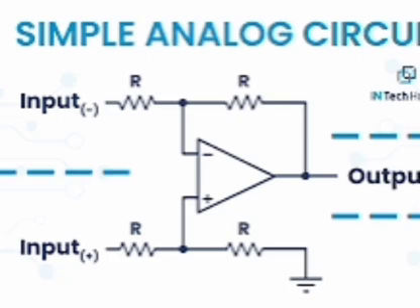Emitter: it is heavily doped as compared to other regions. The main function of this region is to supply majority charge carriers, that is either electrons or holes. Base: this section is very slightly doped and very thin as compared to other sections. Its main function is to transfer the majority carriers from emitter to collector. Collector: this section is moderately doped and has largest area compared to other two regions because it collects the charge carriers from emitter and base. There is a large amount of heat liberation and so it is made with large area to dissipate the heat.